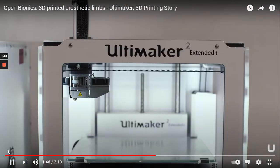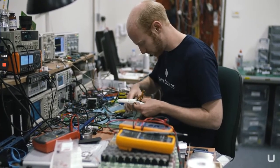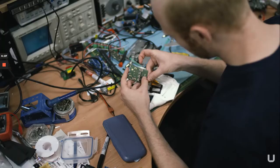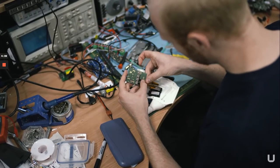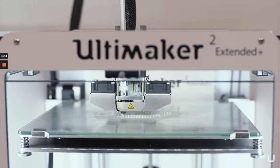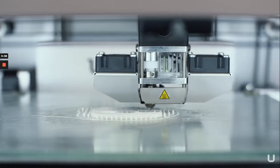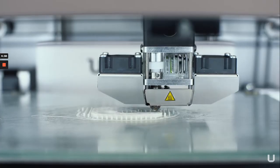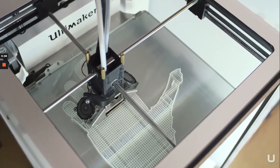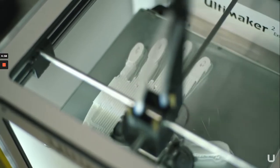We use our multi-makers to print all of the manufactured parts inside of the hand. We have the actuators, that's a component that we buy, the circuit boards we've designed, and we get those made externally. But then all of the mechanical components, we 3D print using our multi-maker printers. We use two different materials at the moment, so we have PLA plastic and a TPU called NinjaFlex, which is like a flexible plastic. So we use a combination of those for different parts of the hand that need to be soft or